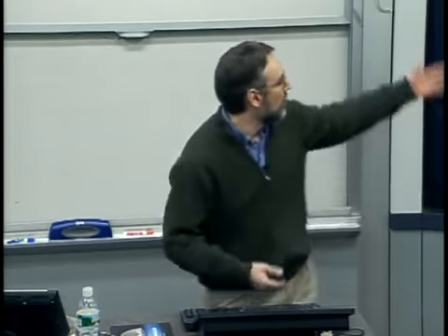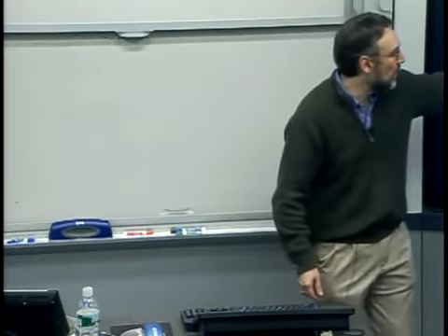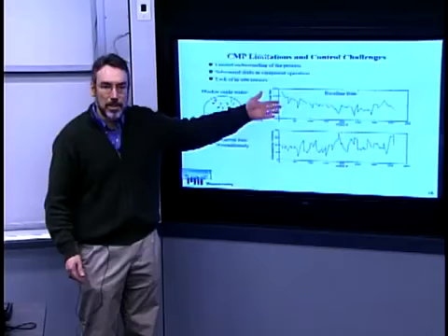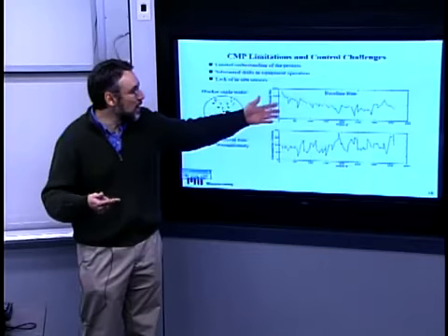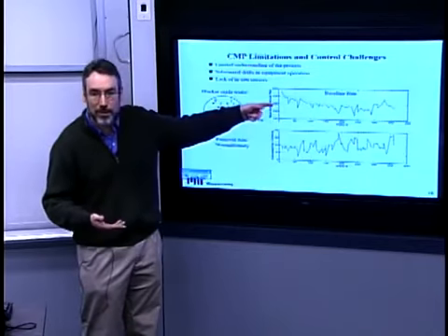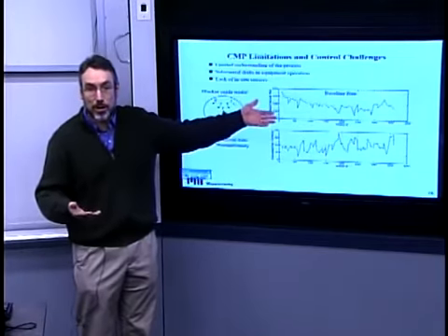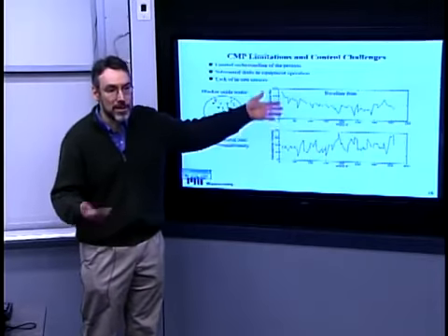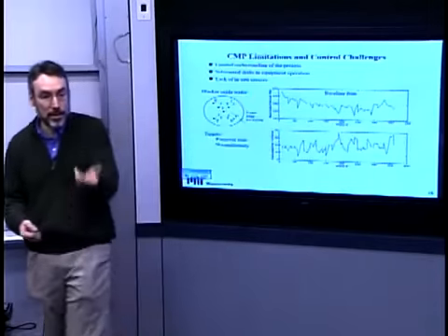I mean, basically, this kind of drift, you could start to think, well, I can measure this, and maybe what I would like to do on subsequent runs, if my removal rate has drifted down, I'd like a strategy where I polish a little bit longer, or I press a little bit harder, these sorts of things.